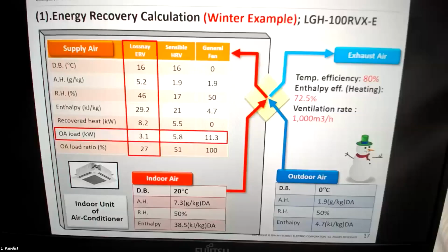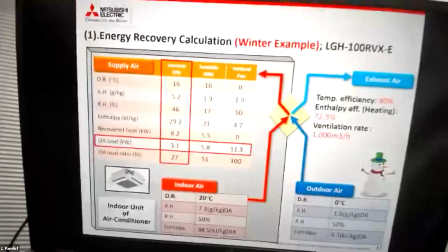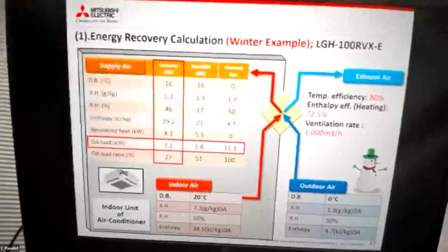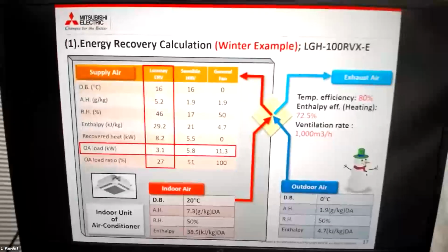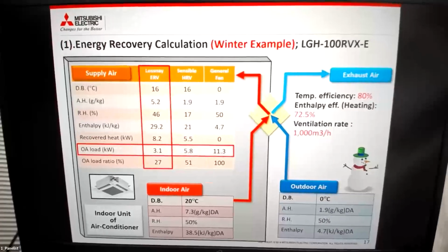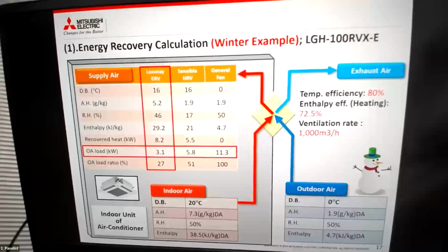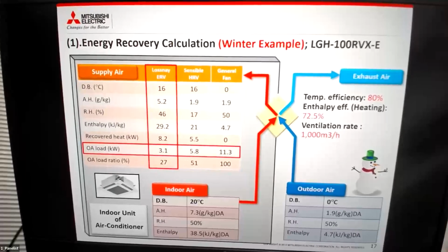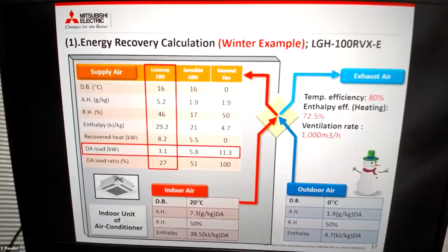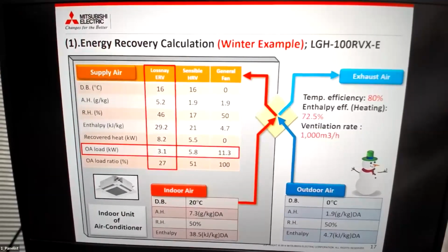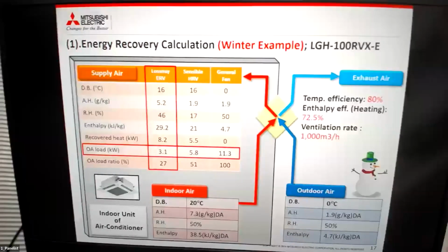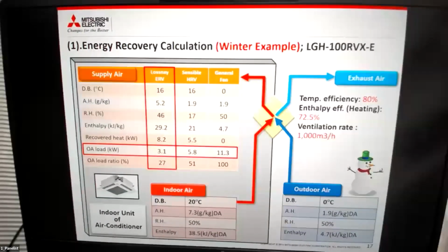And also, a well-asked question is about the heat exchanger. On the surface of the heat exchanger, some dust may be stuck. So every 3,000 hours or 3 months, 6 months, cleaning with a vacuum cleaner is okay. The inside of the heat exchanger is a little complicated structure. However, we have experience over 10 years, 11 years, cutting inside, opening it, and it is basically clean thanks to the filter and mandatory regular maintenance.